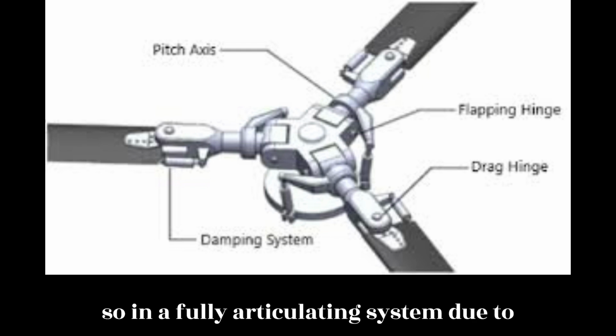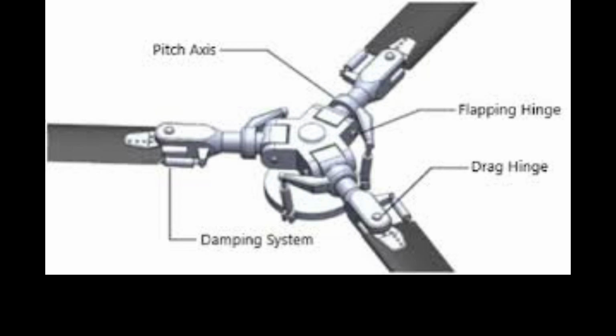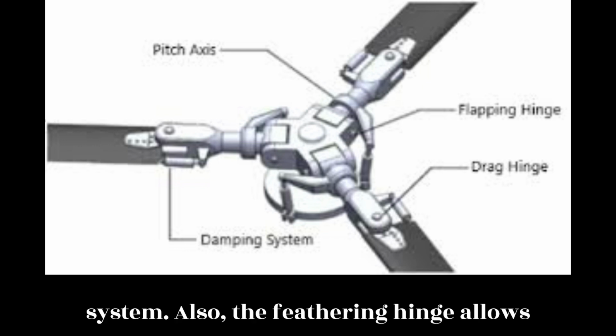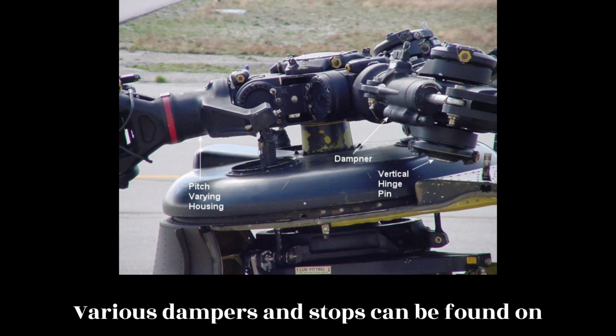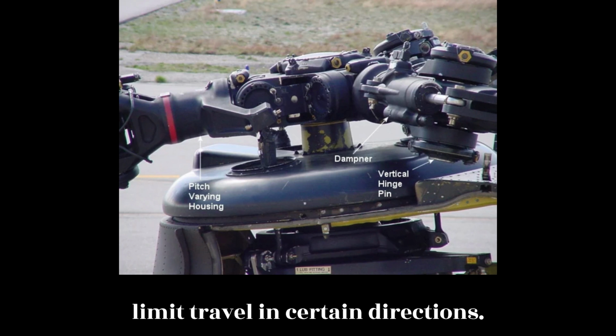They are free to do so in a fully articulating system due to being mounted on the vertical drag hinge. One or more horizontal hinges provide for flapping on a fully articulated rotor system. Also, the feathering hinge allows blade pitch changes by permitting rotation about the spanwise axis. Various dampers and stops can be found on different designs to reduce shock and limit travel in certain directions.